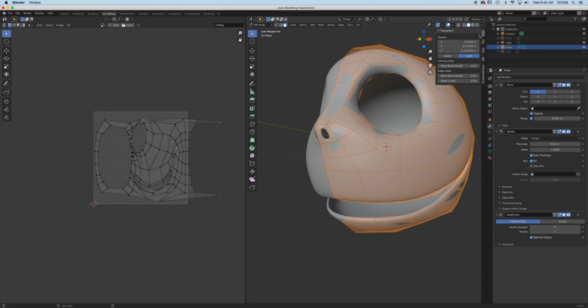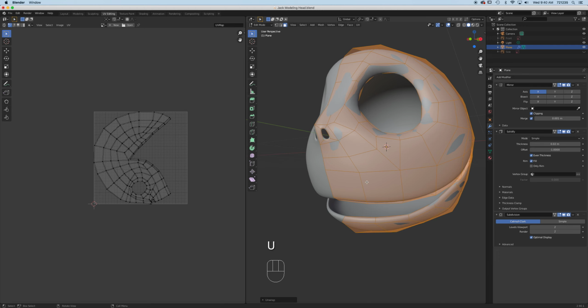So to unwrap, simply go to polygon mode, press number 3 in edit mode. Okay, let me turn on screencast again. All right, and then press A to select everything. Then press U to unwrap, and simply click unwrap. All right, there it is. It's almost stretched all the way, so it's maximizing whatever map we're going to use for it.